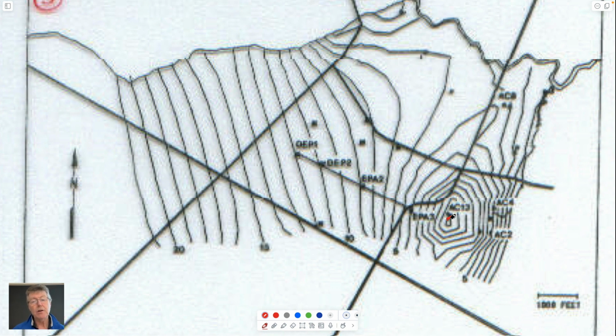You can imagine this being a contour map where you have a depression here, a cone of depression, a valley, which everything is flowing into from the sides. Flow occurs perpendicular to the equipotentials, so it will be brought in from all sides. And the idea is that you pump it out here, you capture the contaminant that is being driven down from upstream, and then you remove it.